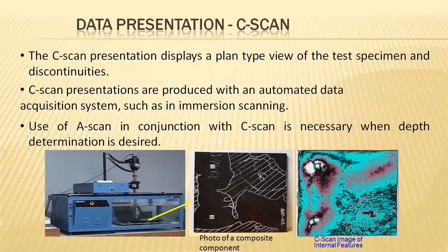We are aware of this immersion scanning, in which the entire specimen is dipped into an aqueous solution, a chemical compound liquid that will identify clearly the surface and the underneath subsurface levels without any air gaps or air medium between the testing tool and the test piece, or nominally the workpiece.